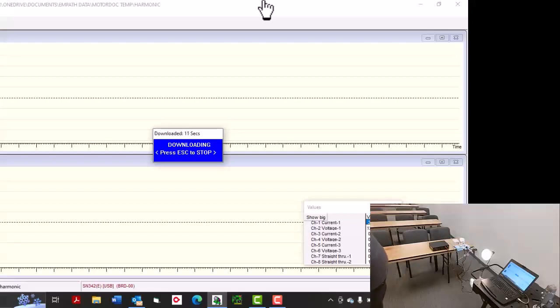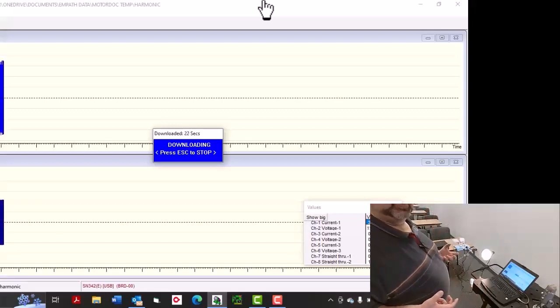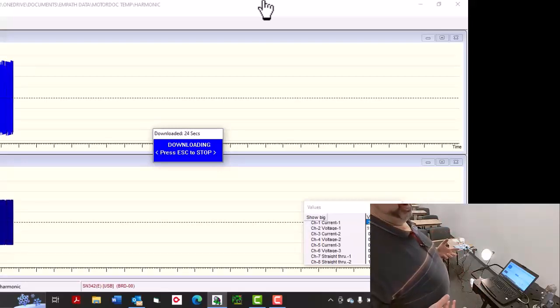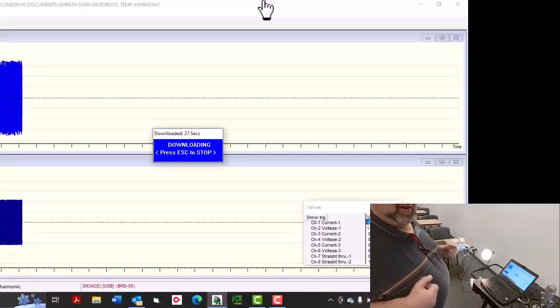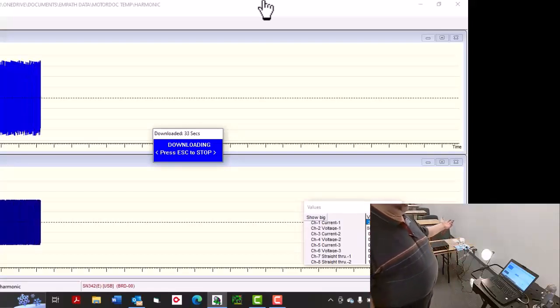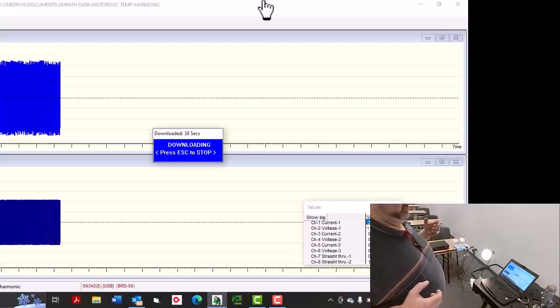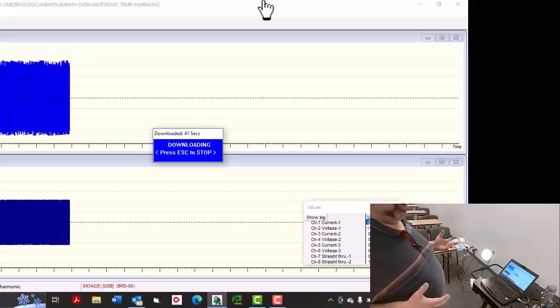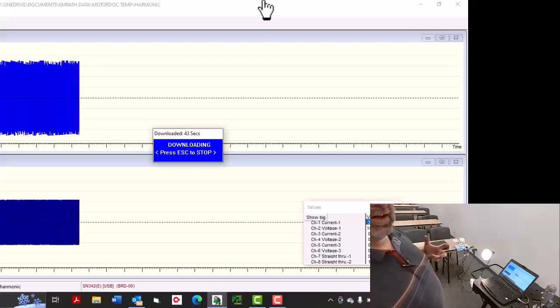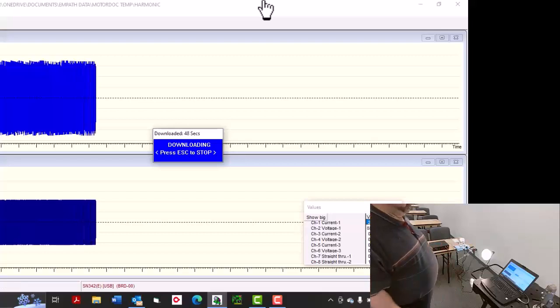So yes, part of tomorrow is also going to be looking at the motion amplification aspect. Now I have done work comparing the two technologies and verifying what we were seeing in vibration versus motion amplification. There was a very, very distinct difference in what I'm showing tomorrow, partially because with the vibration aspect, we're looking beyond the structural, okay? And with the other, we're looking at structural with motion amplification. Knowing that difference is important if you are a vibration analyst or motion amplification person.